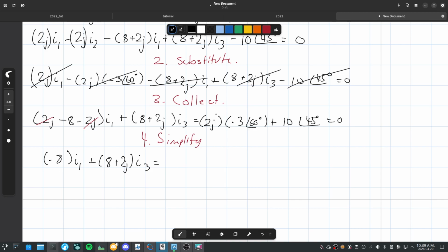Okay, so when you put a negative phasor into your calculator for the 991 ES, you get an error. I think it's because they think you're making a mistake, so they want you to be very clear about it. You have to write negative bracket 3 with a phasor of 60 degrees. This will get you 3 with negative 120, if I'm correct.